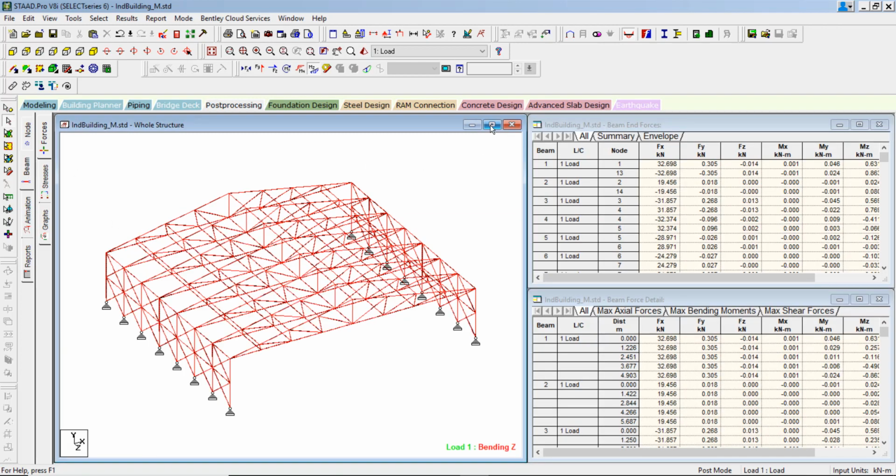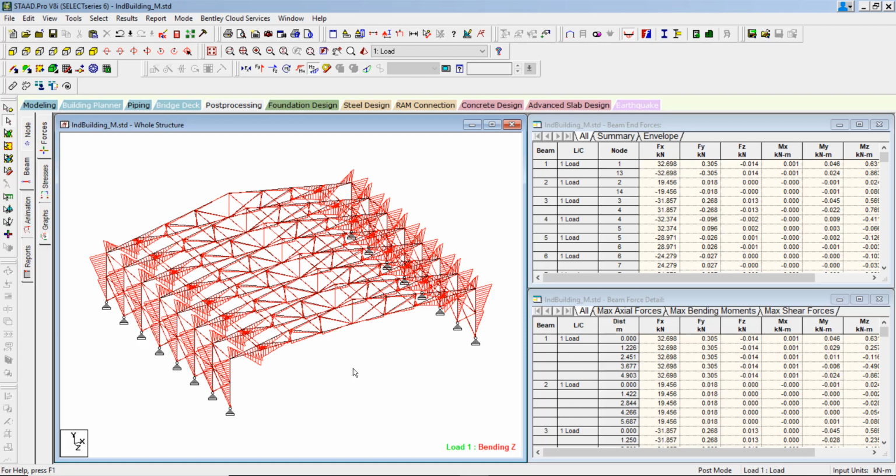All the elements we considered as fully fixed connections, like welded connections, and that's why we never defined any member as a truss member. Rather, we treated all the elements as beam elements, and considered everything as welded over here. Now the analysis has been performed, and you can see the forces, bending moment, and all these criteria graphically as well as in tables.